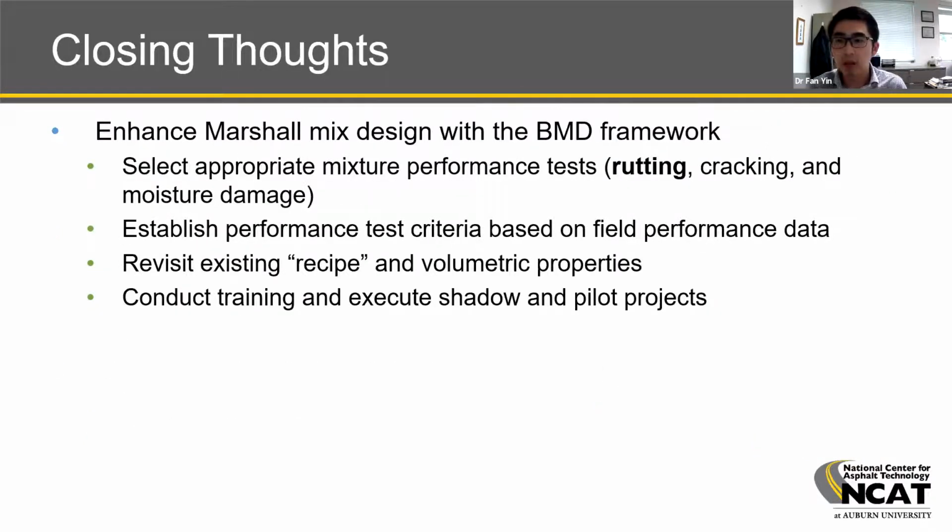Some closing thoughts I have here for discussion or brainstorming with the group: I know you are still doing a Marshall mix design, but I do think there's a way that we can enhance the mix design using the Marshall approach with the BMD approach. We definitely need to look at performance tests. I know rutting is a big concern over there, so we need a rutting test. And eventually, with more traffic and aging of the material, cracking can be an issue.